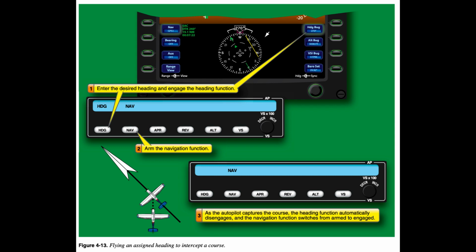2. Determine if the FD/autopilot uses pre-programmed intercepts or set headings for navigation course interceptions. 3. Determine the indications of navigation mode armed conditions. 4. Determine parameters of pre-programmed intercept modes, if applicable. 5. Determine minimum and maximum intercept angle limitations, if any.